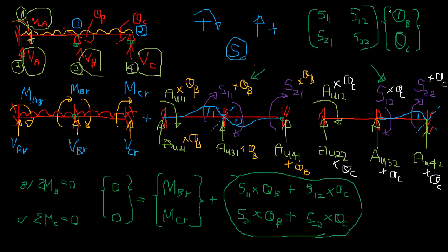So can you see here you have curly brackets, right? And here you have square brackets. Why? Actually, these forces are for a unit displacement. In this case, it is unit rotation. So these are not going to change on your external loading, because these are derived for a unit force, unit rotation. In such case, we use square brackets. These are changing, right? So these change on your external loading. So that's why we use curly brackets.